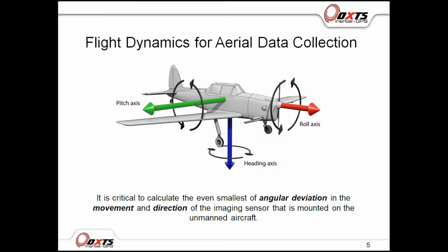The accuracy of the resultant georeferenced image will be dependent on the volume and density of ground control points surveyed, which leads to increased field time during the operations. There may also be health and safety implications when sending ground surveyors to a site, which could of course also be the reason why aerial UAV mapping applications might have been deployed in the first place.